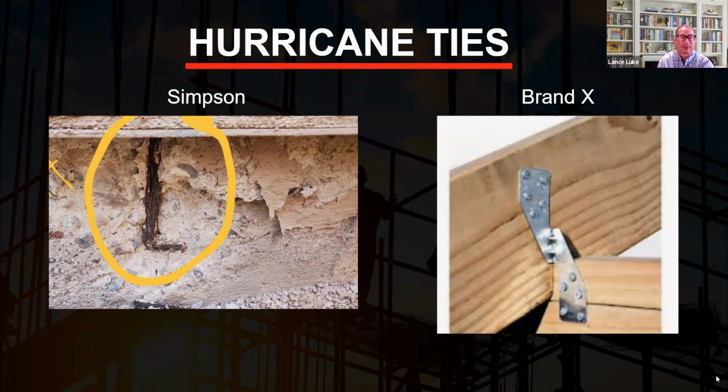And then on the left, you have this anchor bolt, which is in the shape of a J. Construction-wise, when they form the concrete slab, and I'm talking about a single-family house or a condo, okay, before they pour the slab, they put these anchor bolts in.